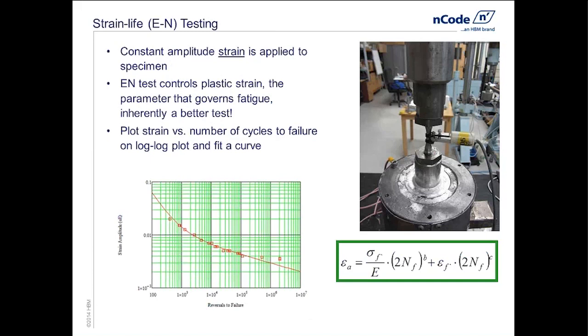When we do fatigue, we have a variety of different damage models we can use. We're going to focus on StrainLife or crack initiation. And in order to do that style of analysis, we need to have a StrainLife curve. The StrainLife curve is actually developed with a series of constant amplitude strain tests.